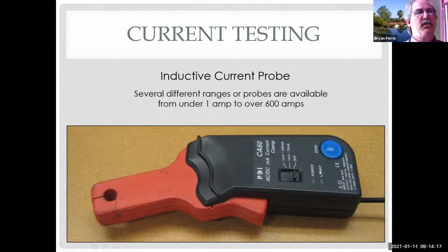So this allows me to use this with any voltmeter or lab scope because I'm converting it to volts, which all the meters do. The other advantage of this is there's no fuse to blow. So you can see, even though these are around $100, how many times do you need to blow some fuses in your meter to pay for this? Right? So, you know, there's an advantage to that. Also, if you notice down here, it says Cat 3, 300 millivolts plus or minus Cat 3. So this is acceptable for a lot of DC hybrid work going to the batteries.